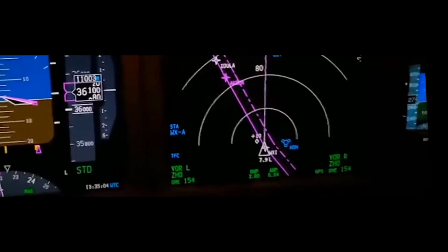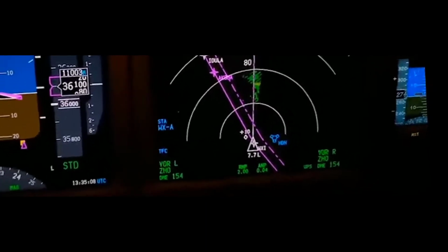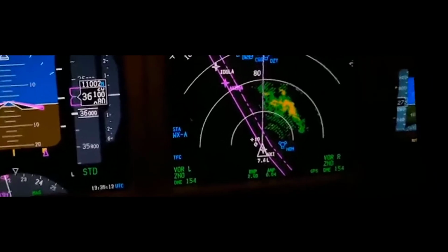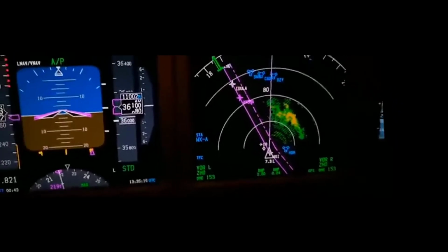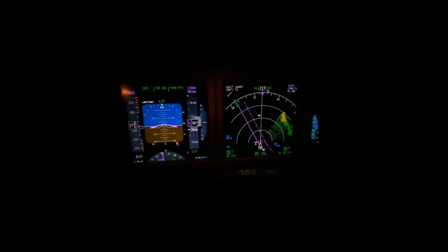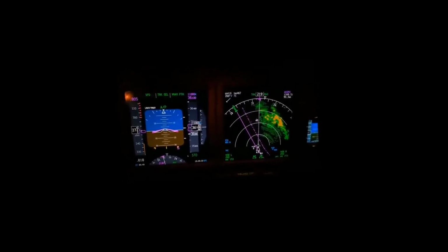This will normally show up on the radar display as a very thin line that will start at the apex of the screen and continue to the edges, no matter which range you are set on. This will almost always appear at the same spot on the screen, as shown on this video. Here are some examples of intermittent antenna resolver wiring which caused spoking.